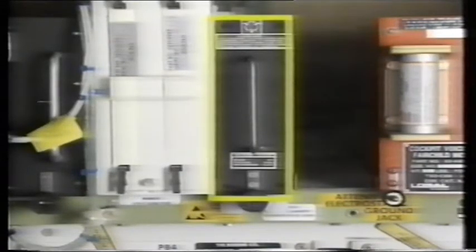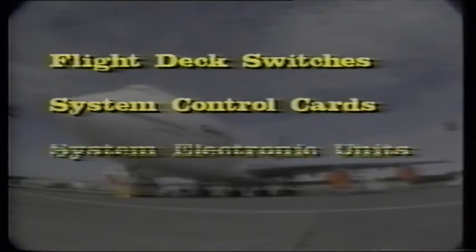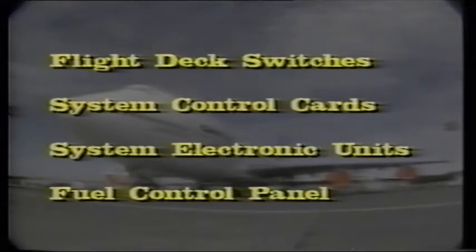In the center fuselage equipment center is the fuel quantity indicating system processor, or FQIS processor. In the aft equipment center, the remote electronics unit. It supplies fuel quantity information to the FQIS processor. Mounted in the leading edge of the left wing is the fueling control panel. It controls the fueling process and provides fuel quantity indication. In review, flight deck switches, system control cards, system electronic units, and the fueling control panel provide fuel system control.